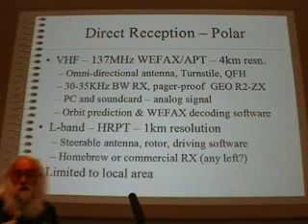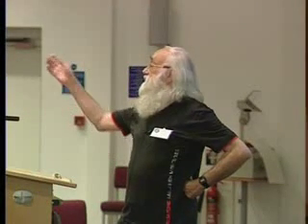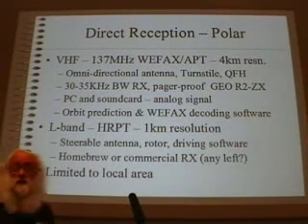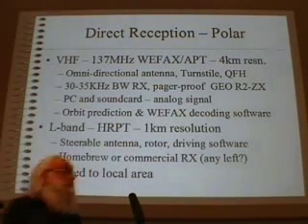So, polar orbiting satellites, we've got 137 megahertz, and you may have seen outside the turnstile antenna that Francis Bell has been demonstrating polar orbiters from. Great advantage of that is that you don't actually need a steerable antenna. You can manage without.